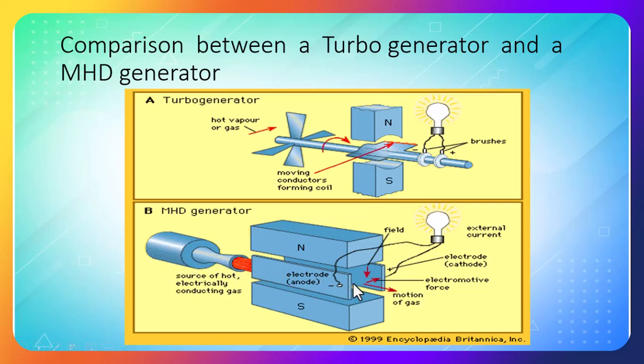When you pass it here, that hot air will become a conductor. When the conductor is moving, here you have made a conductor with the help of wires and solid copper that is being rotated by this turbine, whereas here the air is going to move from this end to this end. Which means you have a moving conductor-like structure. That is what we required. The north pole and south pole, you have kept them. You are going to pass the gas here. On these two ends you will try to generate power. That is what is followed in an MHD generator.